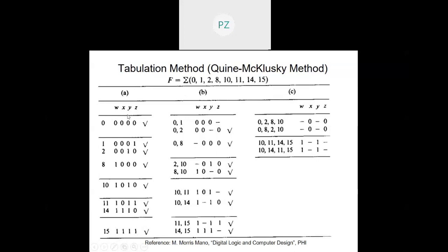So to begin with, we have taken an easy example where the sequence itself was such that they may be grouped as per the number of ones in each of those min terms, right? We'll take also the examples where they may not necessarily be sequenced according to the number of ones in them. But as of now, the first step is to group them as per the number of ones in each of those min terms' binary representation. Now, first step completed.